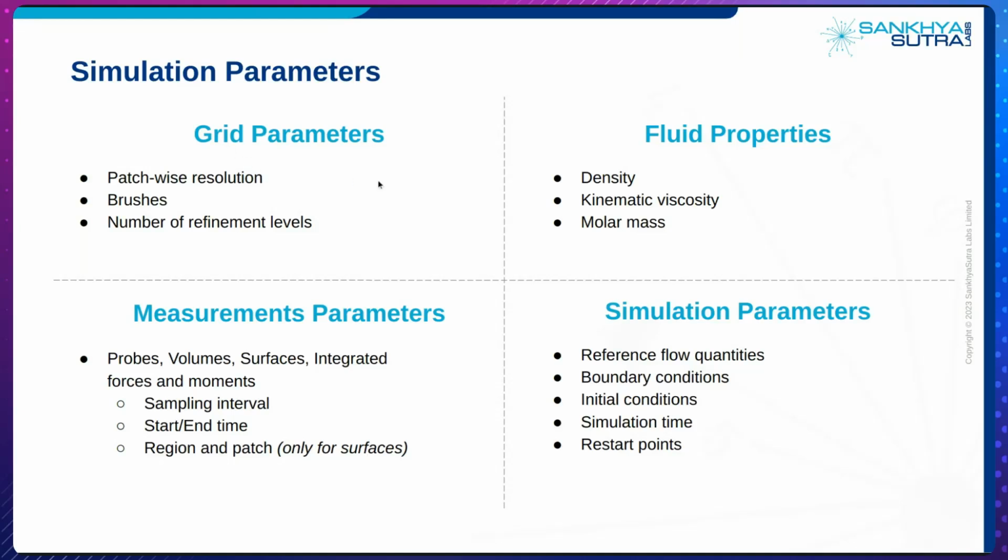So Taral offers features such that you can set custom resolutions for specific surfaces of your STL. Brushes are essentially a feature where you can select specific cuboidal regions in your STL that you want resolved with a certain level of accuracy. Number of refinement levels essentially determine the number of resolution jumps that occur from the finest resolution in your simulation to the coarsest resolution in your simulation. All of these things will become much clearer as and when I show you the demonstration itself.